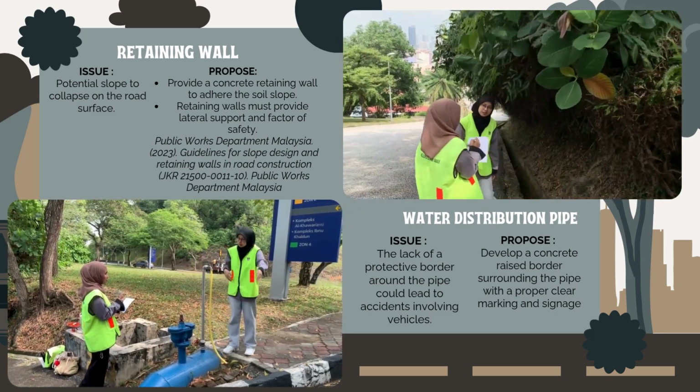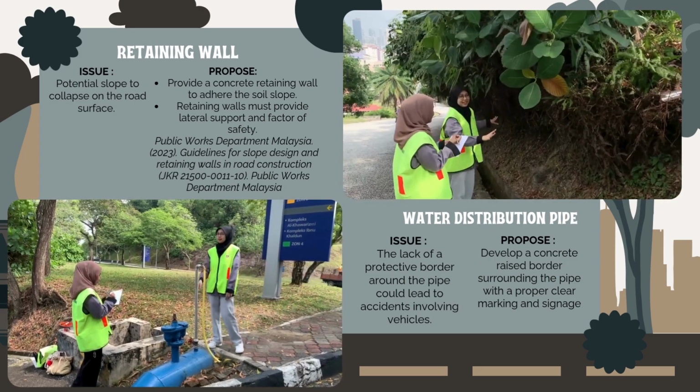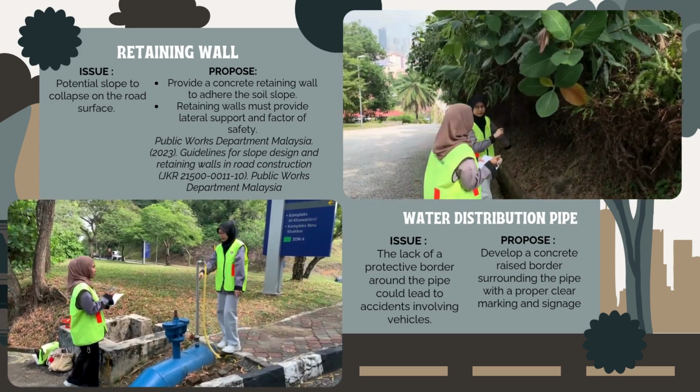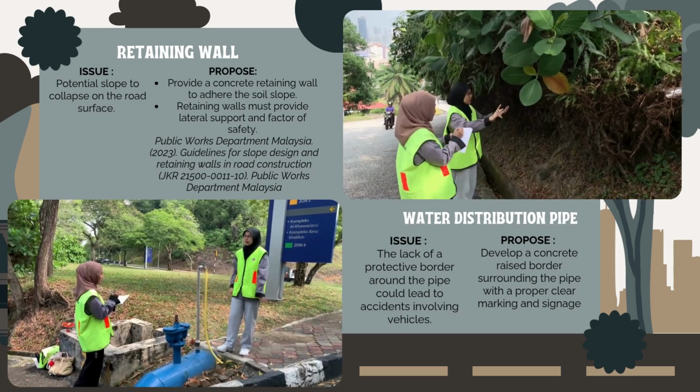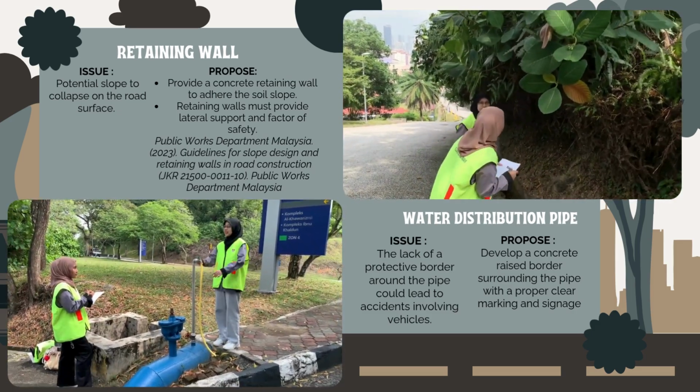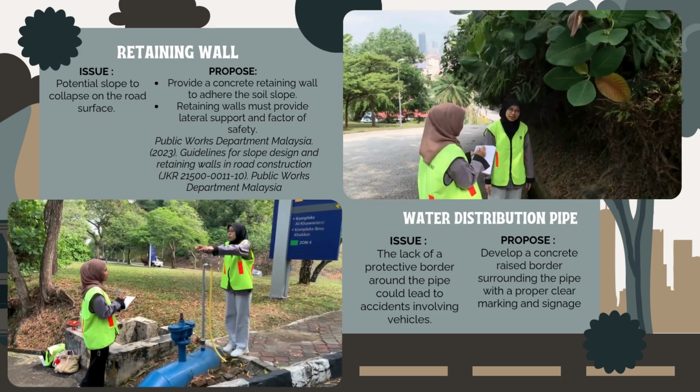The next one is retaining wall. The issue is potential slope to collapse on the road surface. We need to provide a concrete retaining wall to hold the soil slope. The retaining wall must provide lateral support and factor of safety according to the Public Works Department Malaysia.